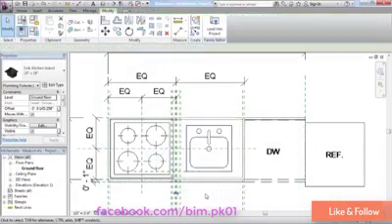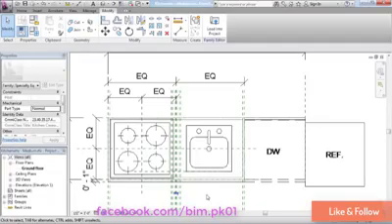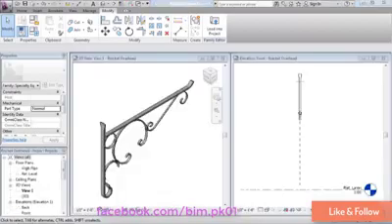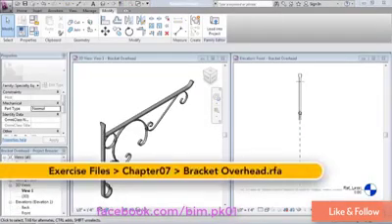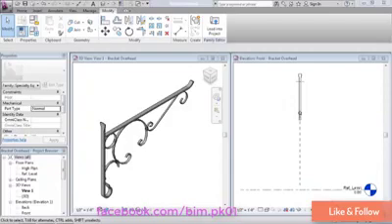And when you get to your project environment, when you change views from either a plan or an elevation or change the level of detail to coarse, medium, and fine, the families will respond accordingly with a correct and appropriate level of detail. Revit determines what to display in a plan view by the View Range dialog. Any element that is at or below the cut plane will display in plan, and typically those items that are above the cut plane will not.